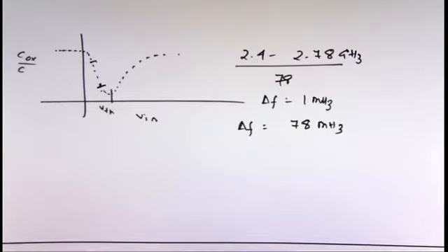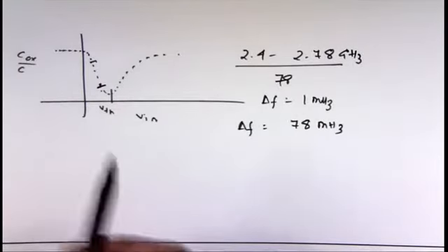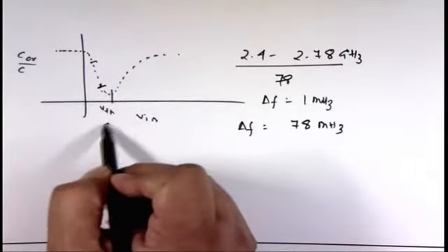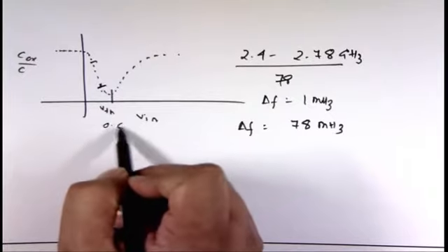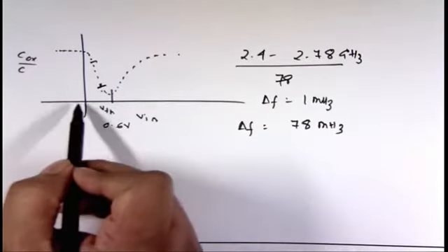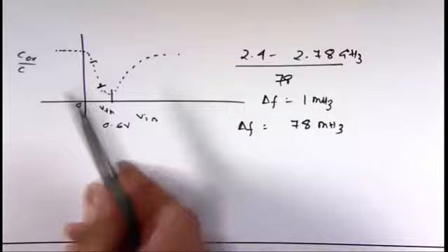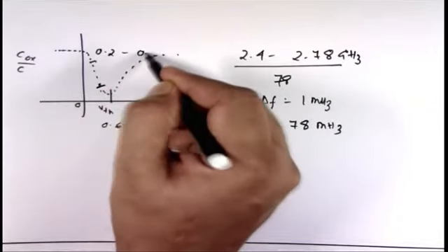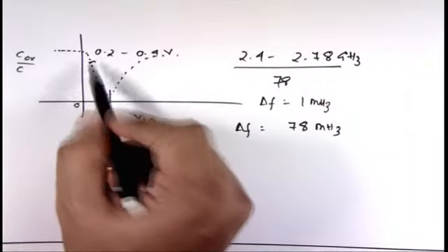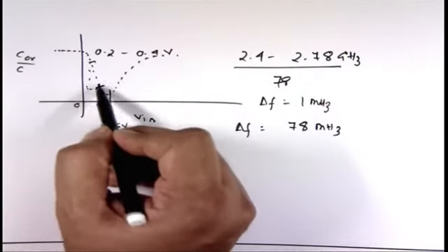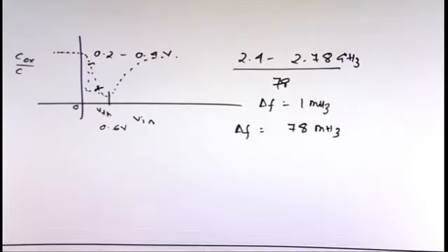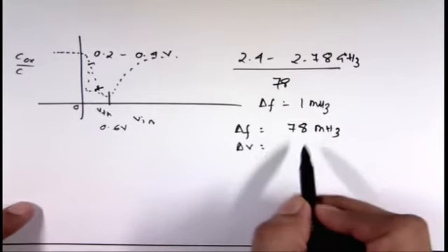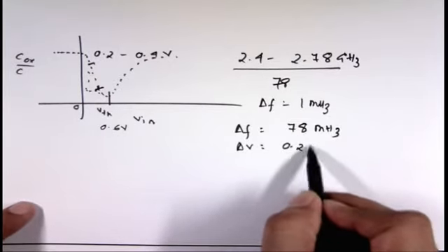But look here, for 1.8 volt systems, like 180 nanometer, your threshold voltage VTH is 0.5 or 0.6 volt. So you can vary it from say 0.2 to 0.4 volt to have the operational linearity; this is the operational region of your voltage. So your delta V equals 0.4 minus 0.2, equal to 0.2 volt.